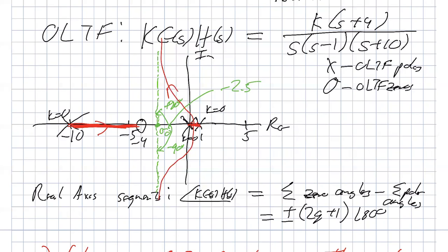And this one goes towards this zero out in infinity. It's way out there, so I'm not drawing a real zero. And likewise, this one comes down here, and it is going at some imaginary zero over here. So you can view these lines here as pointing the direction where those zeros are at, and we're going to asymptotically approach them.